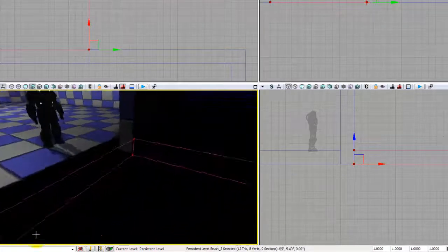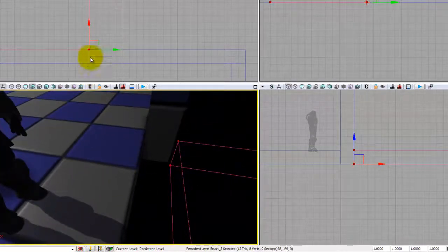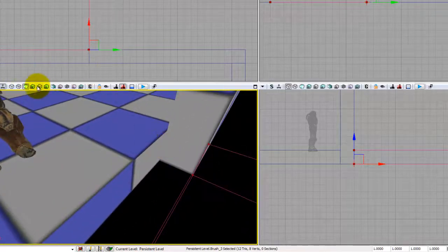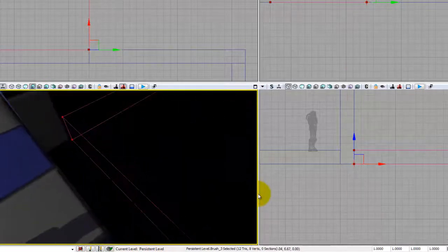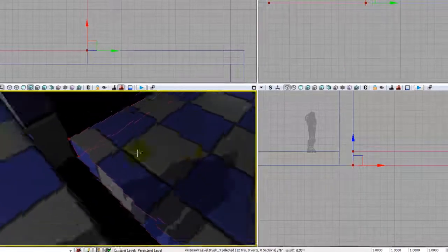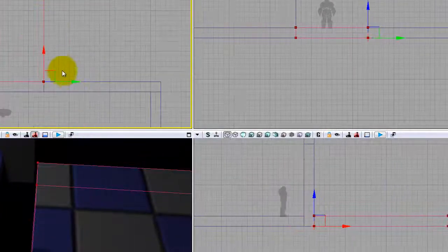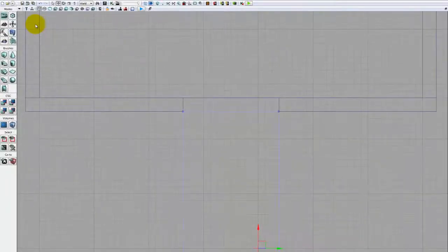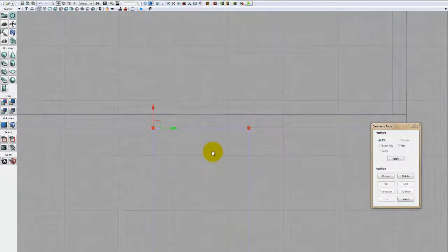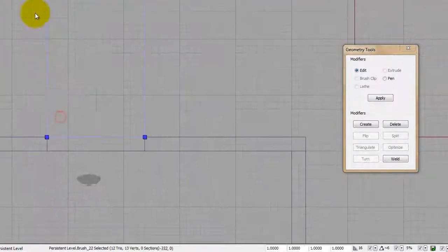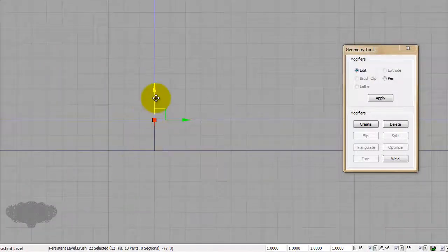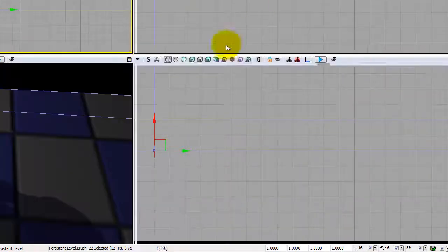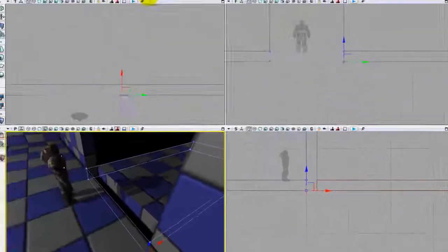And if you notice here, I actually didn't make it long enough because I was lining it up with the outside wall. And if we look here, there's actually a gap here. So if I add this, hit Control A, you'll notice there's a gap in between the floor here, and that's just because I didn't drag it far enough when I made it. So I'm going to come back into my top view, Shift 2 to get in geometry mode, Control and Alt to drag, and then I'm just going to move this into place here. And it looks like it's overlapping, but it's actually not. We're just seeing the roof portions here, they overhang a little bit. So now I'm going to hit my rebuild geometry.